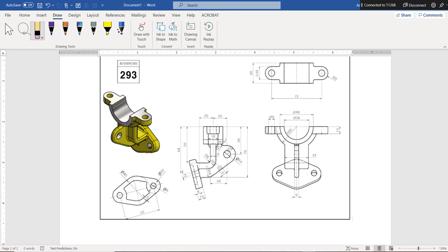I have many issues with how this drawing is detailed. From dimensions being inside parts, see that? That's a big no-go. We never do that, okay? To this, which makes me horrified to see this dimension there. You would never dimension a diameter like that. That's a big no-go. So when you look at this drawing, please appreciate the reality that it is nowhere close to perfect on detailing. Got it? It has a lot of bad habits in it that are really, really bad. Okay? You shouldn't do most of what's on here.